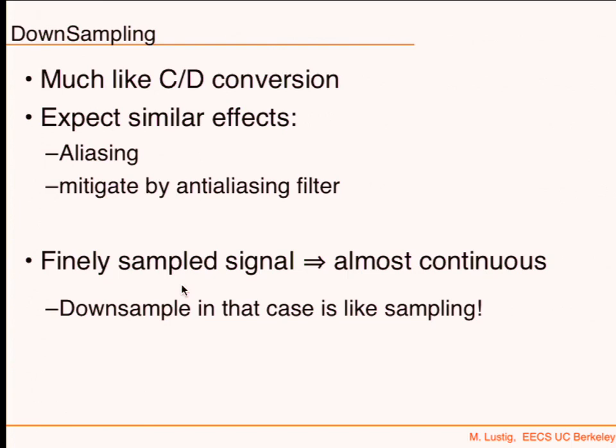And so what we're going to do now is talk about how to change the rate of a discrete time signal, because let's say we sampled at 240 kilohertz using our RTL SDR, and then we demodulated something like FM, and we want to go down to 48 kilohertz in order to play it on the sound system on the computer, because that's what it would accept. It would not accept anything different or higher. It would not accept 240 kilohertz for sure. So what do you do then?